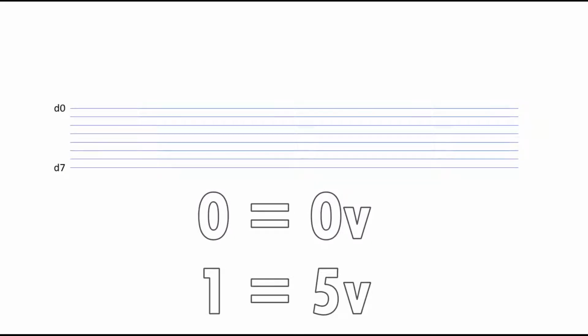So we would put 10101010 on the bus, and we would be transmitting the number 170 on the bus. So anything that's connected to the bus would be able to read that value 170 off the bus. So when we say we put a 0 or a 1 on there, well, a 0 is 0 volts and a 1 is 5 volts. So we put either 0 volts or 5 volts on a line of the bus in order to set it to either a 1 or a 0.